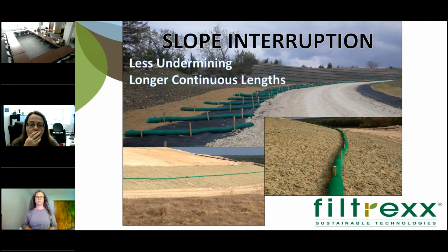Another alternative, you can use this for slope interruption, as you can see here on this slope. Sometimes you'll see a straw wattle used, which is another product that we also can get. The silt sock again is a little bit more hardy. It's going to get a longer lifespan out of that. If you need a slope interruption in place for a while, it's a good way to go.